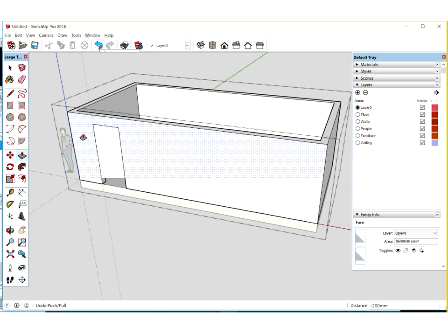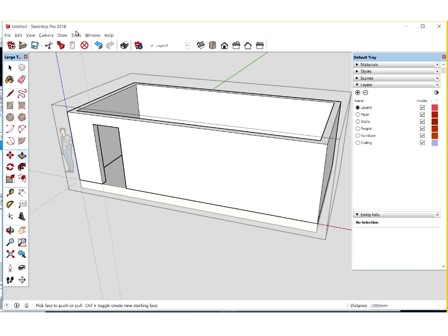You'll know if you've divided that wall into two different regions, because you'll see that grid of blue dots that show that it can be selected. Sometimes if you draw a shape onto another shape, if you didn't double click on your group, it won't work, that type of thing. So push pull to that offset limit of 200. Sometimes you get to jiggle your mouse around until it tells you it's on that face. Click again, and once you've successfully cut an opening there, put up a green tick.